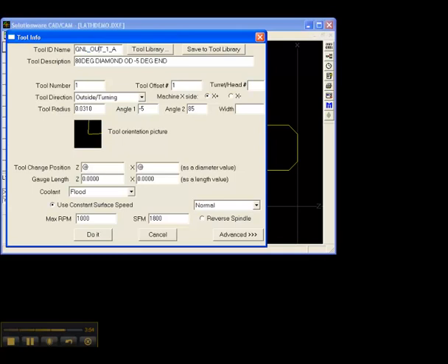And then you put in another underscore and the number that you want to use for that tool, and another underscore and the letter, if any, that you want to use for that tool. For G-code users, or for earlier style Mazak controls, Fusion 640T and below, you want to use the tool number field. That's the third row down here on the left.